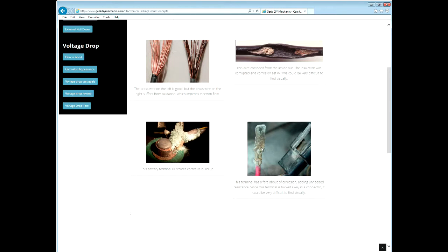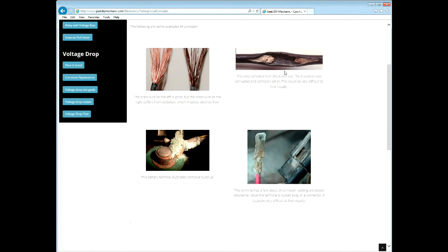And these sorts of issues, actually these two right here, are hard to find, because who would think to take apart all your connectors, and you're afraid to do it because you may break them, yet in one of them could be the corrosion affecting your circuit. As you can see, corrosion can be very obvious, like the battery terminal, and unfortunately very stealthy to detect, illustrated by the wire corroded from the inside out, like up here, or even the connector, like I was saying.